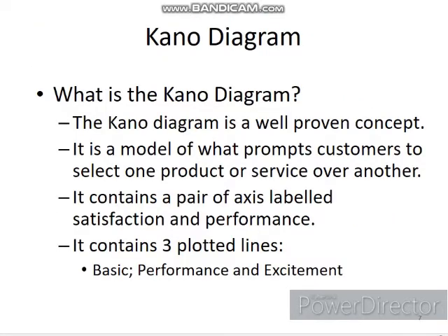As I mentioned just now, in QFD the most important thing is the voice of the customer. So based on customer requirement and input, you want to meet and exceed the customer requirement. In meeting and exceeding the customer requirement, there is a tool called the Kano diagram. This tool is very good for identifying how to meet the customer requirement: what features in a product you need to fulfill to meet the customer requirement, and what features of a product can exceed it.